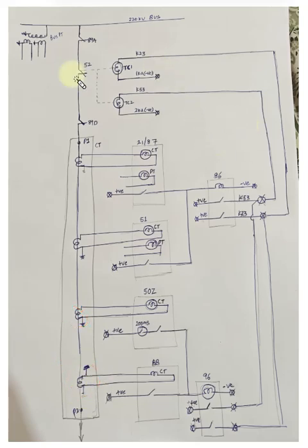Okay, so the breaker has two tripping coils, trip 1 and trip 2. For redundancy, we have used two tripping coils because protection is very important, and a negative is continuously being given to both tripping coils, and the positive is being extended from the 86 master trip relay. Here the master trip relay we have shown. All right, so we'll start with the first relay, that is the main protection, distance or differential.